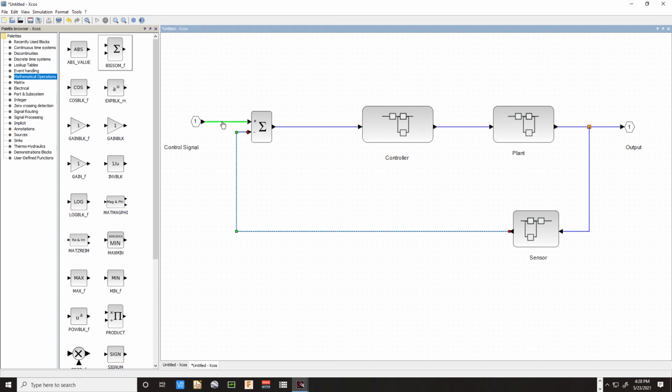So if we're putting in temperature here as an example, this says, oh, the temperature's high. It puts out a positive number. The controller sees that positive number, says, turn on the air conditioner. The air conditioner turns on and runs for a while, and as it does, this sensor sees the temperature coming down. And when that temperature comes down to where it's near this, the difference then becomes nearer and nearer to zero. It gets within a gap. Our controller has to take that into account, and it says, fine, it's time to turn the air conditioner off. It's cool enough.